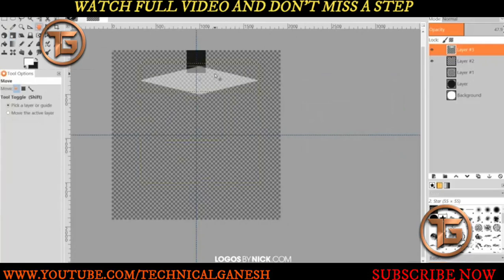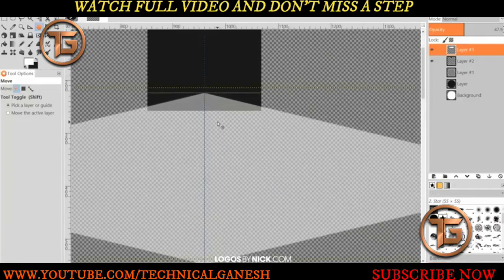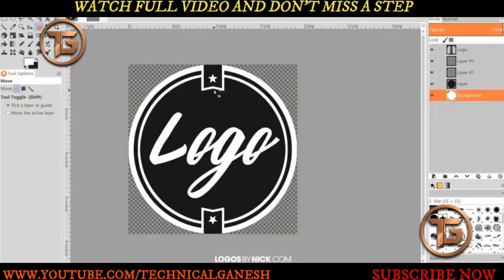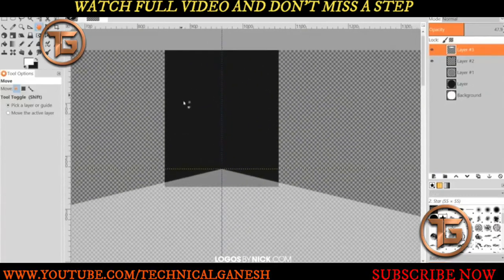And I'm going to grab the Move tool. I'm just going to position this at the center of the page. It should snap onto the guide there. Let me zoom in on this area right here by holding Control and rolling up the mouse wheel. I want to snap this to the center of the page and bring this up to right here so that this white area is intersecting with the black tab right there. And if you see where I'm going with this, if you notice the shape of this tab right here, I'm using this as a reference point to punch a hole through this object here.